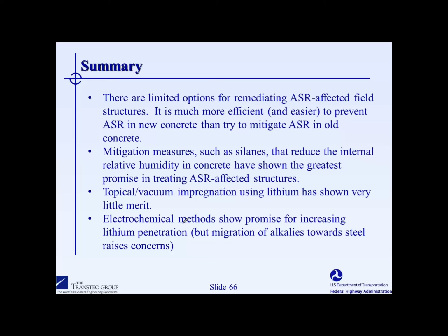If you have, say, a bridge deck or a pavement and you have vehicular traffic applied to it that might abrade away the top layer, we do know that you will have to reapply earlier because you're losing that treated surface. But in the case where you have structural elements that are treated that don't have any abrasive action at all, the only other thing that could really impact the durability of silane would be the UV effects. And we really haven't seen that with the Canadian experience.